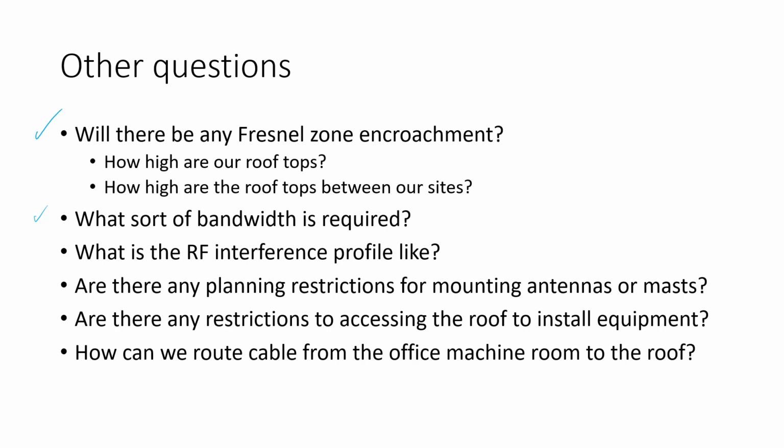And all of that bandwidth will be in part dependent on how much power you're going to get across to the receiver. If you're very close down to the safe system operating margin, then you might be talking about very low data rates. But if you've got, like we have, a good 20 dB above the safe system operating margin, you're going to be absolutely fine. So you should get a good data rate.